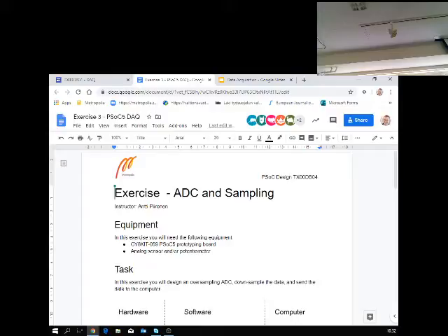No. Okay. You connect 1 and 3 between ground and the operating voltage, and then terminal 2 gives you the signal. But this is actually quite nice. You can easily test if your ADC converter is working.